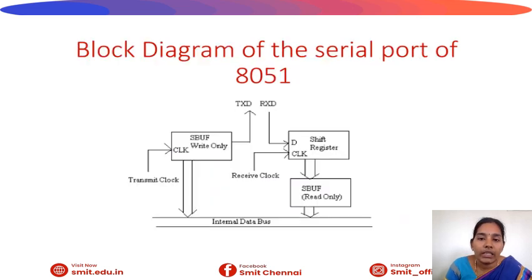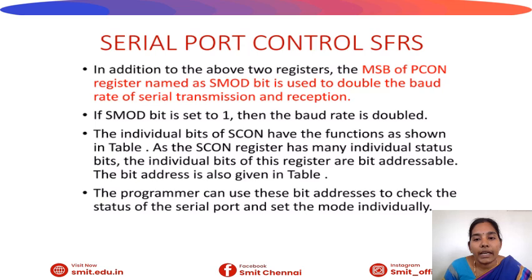This is the block diagram of the serial port of 8051. You have 2 registers, the S-buffer register for read and write. You also have shift registers. TXD and RXD are the input-output data signals. Additionally, we have the internal data bus for transmitting the data. In addition to that, the PCON register has the SMOD bit. SMOD doubles the baud rate of the serial communication.